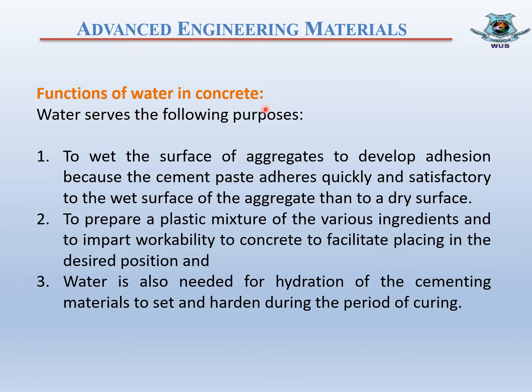Functions of water in concrete. Water serves the following purposes in concrete. First, to wet the surface of aggregate to develop adhesion, because the cement paste adheres quickly and satisfactorily to the wet surface of the aggregate rather than to a dry surface. Then, to prepare a plastic mixture of the various ingredients and to impart workability to concrete to facilitate placing in the desired position. And finally, water is also used for hydration of the cementing materials to set and harden during the period of curing, and it is the most important purpose of water in concrete.